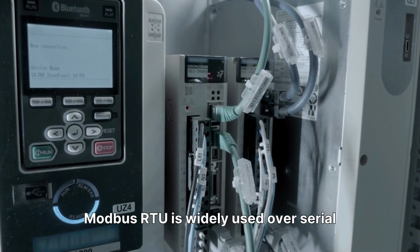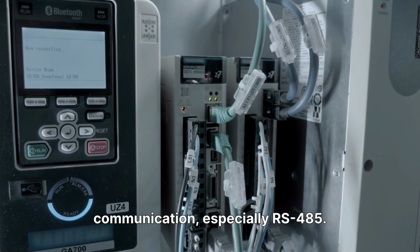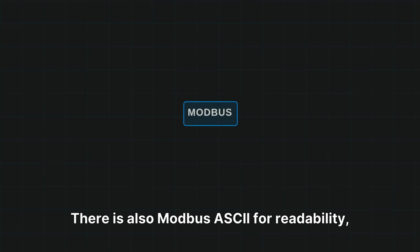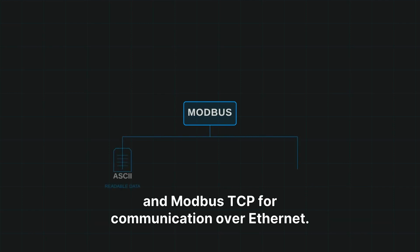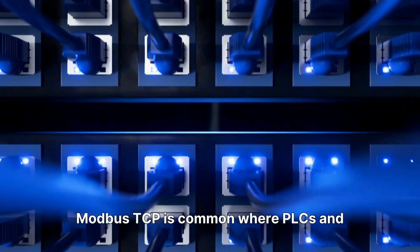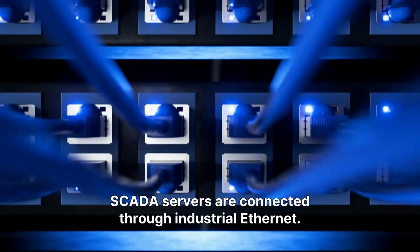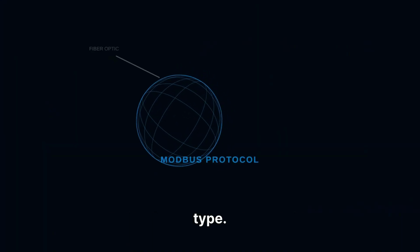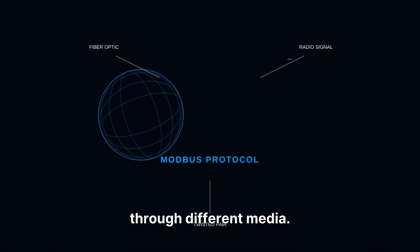Modbus RTU is widely used over serial communication, especially RS-485. It is compact and efficient. There is also Modbus ASCII for readability and Modbus TCP for communication over Ethernet. Modbus TCP is common where PLCs and SCADA servers are connected through industrial Ethernet. So Modbus is not just one cable type. It is a language that can travel through different media.